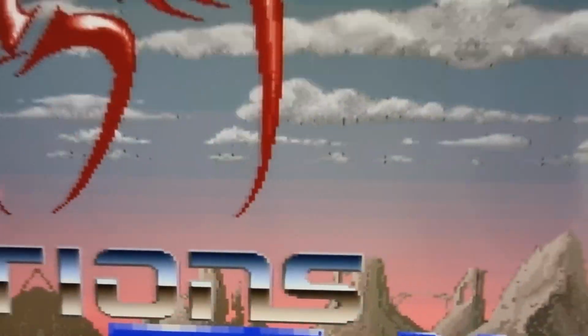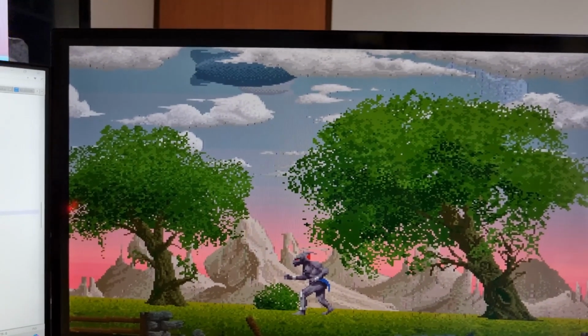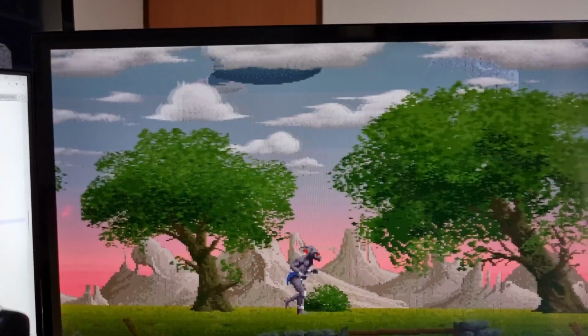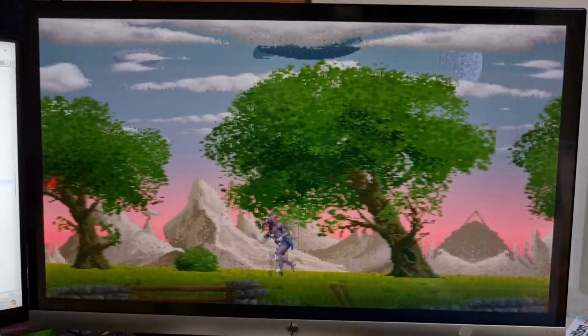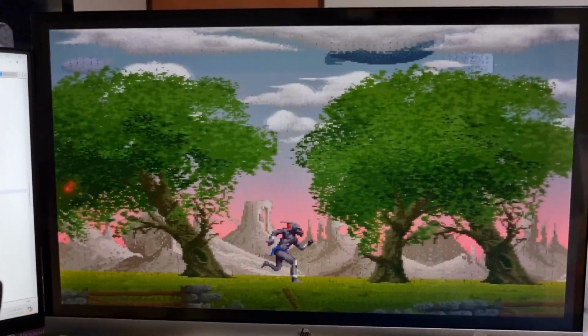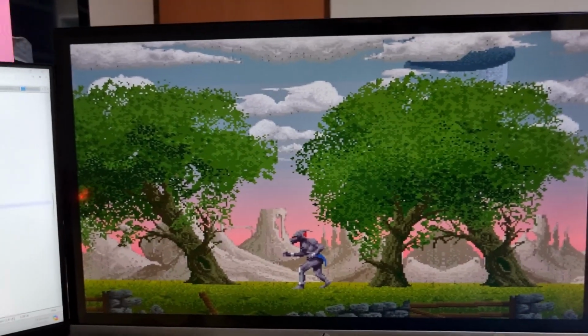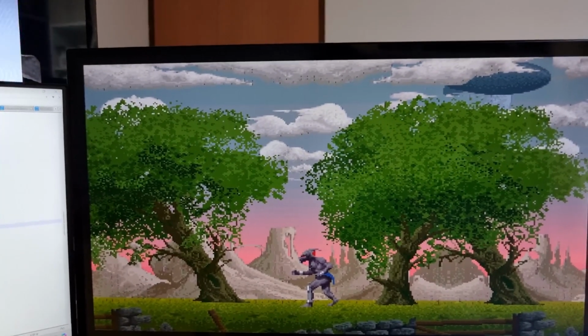The extended interface is running in pass-through mode in this demo because it's not using any of the DMA functionality currently. It's using the APU and all of the scaled sprites and normal sprites and the tiles layer and the characters layer, of course. And the APU allows those rather lovely background color gradients, and of course also the parallax scrolling layers as well. The APU is handling the raster splits there for the parallax scrolling layers. So yes, all that works perfectly well.